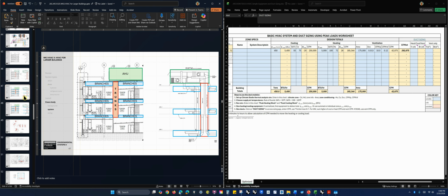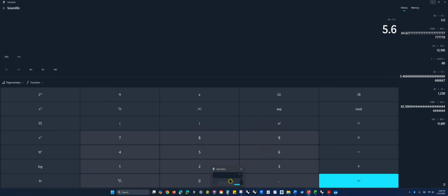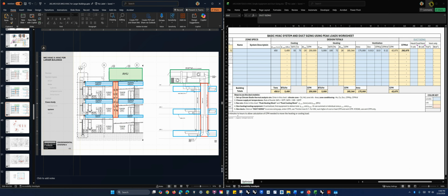We're saying that each of these supply ducts going down is about 6 square feet. Is that what we said? Make sure. Yeah, 6 square feet. So 2 by 3. Now that seems a little small to me, maybe, but maybe not. These aren't really huge zones, but it's definitely reasonable. And that's what we're doing here.